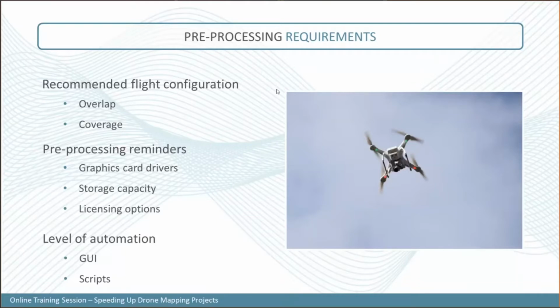If it's not possible and you're trying to map a large area, what you can do is sometimes split your block into smaller sections, and then derive a flying altitude to have a constant GSD on the whole area. So that's another approach you can use for your drone project.